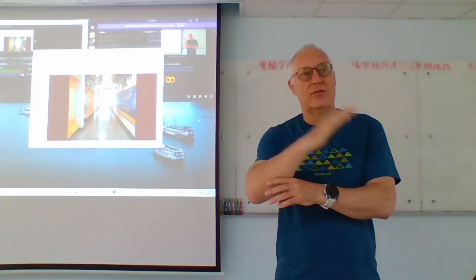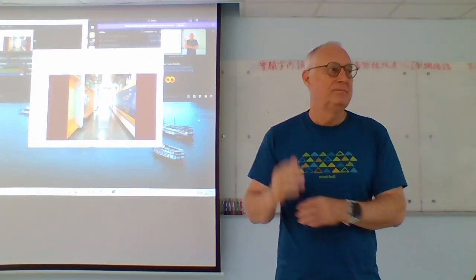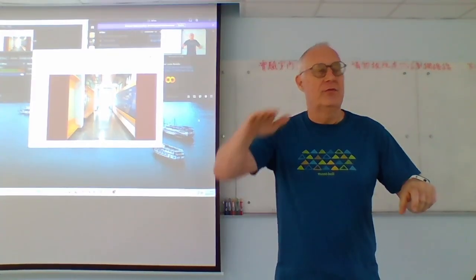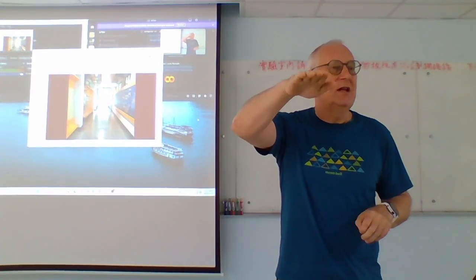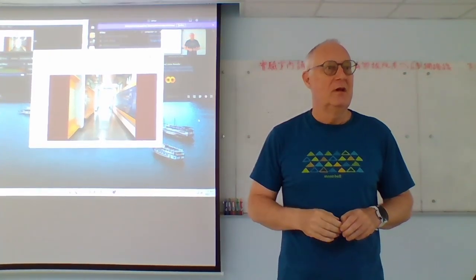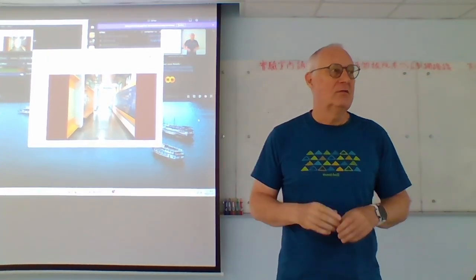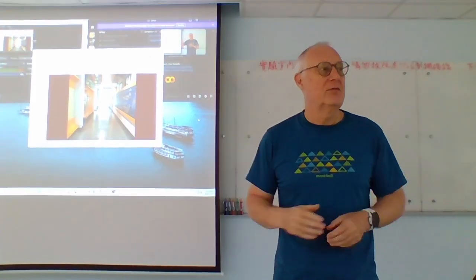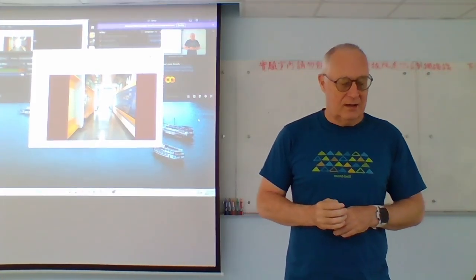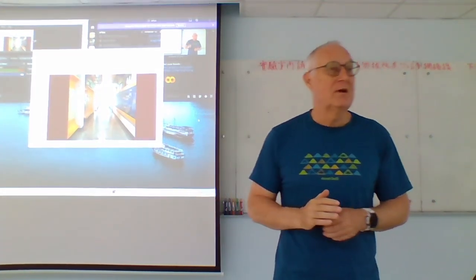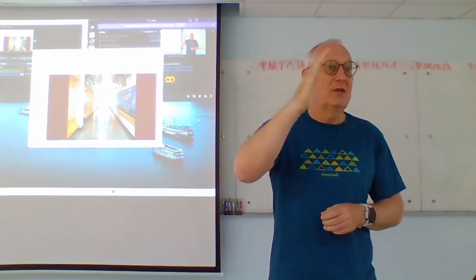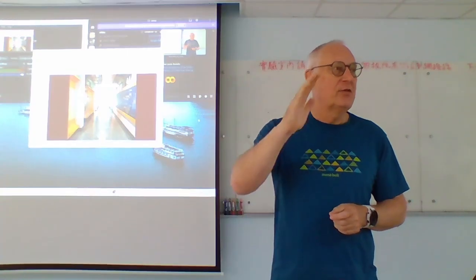Because there's a nice value that it can measure. But if the robot is sort of not rotating much, balanced, then there's not much angular velocity, so the errors kind of drift in. But if the robot doesn't rotate very much, right? If it's at a stable angle, that means that the accelerometers are actually very nice and accurate.